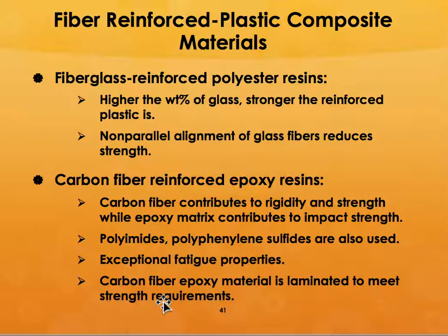And carbon fiber composites, as I mentioned to you in the last class, have exceptional fatigue properties. Most of the time, what we do is we have single sheets of carbon fibers with fibers oriented in specific directions, and they are laminated to meet the strength requirements in the direction of the loading or the direction of the stress.